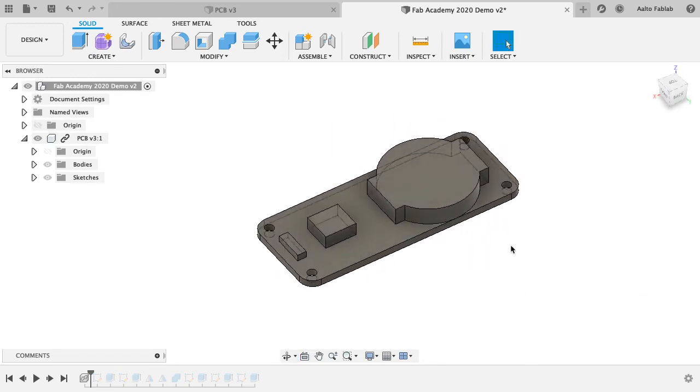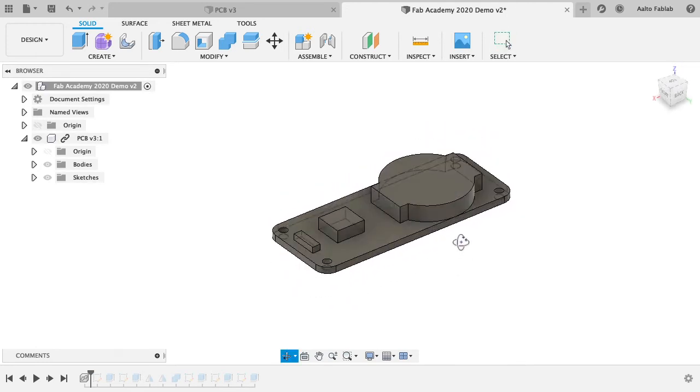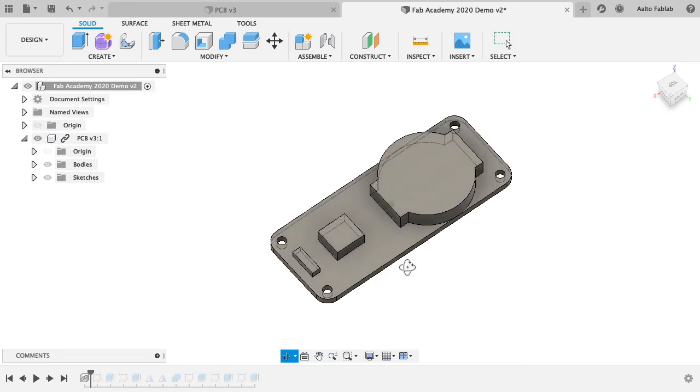So usually for parts like motors, it is possible to get step files from the website where you buy them from, or from part repositories, and then you can import these step files into your Fusion 360 model design and use them as references for designs. In a similar way as these Fusion 360 files. And now, let's just make a simple case around it.